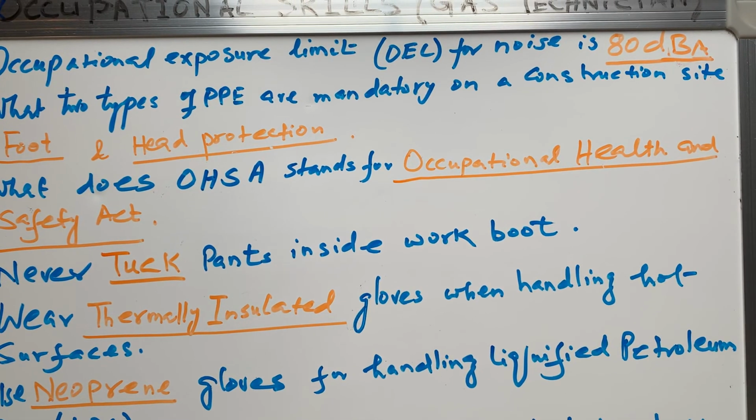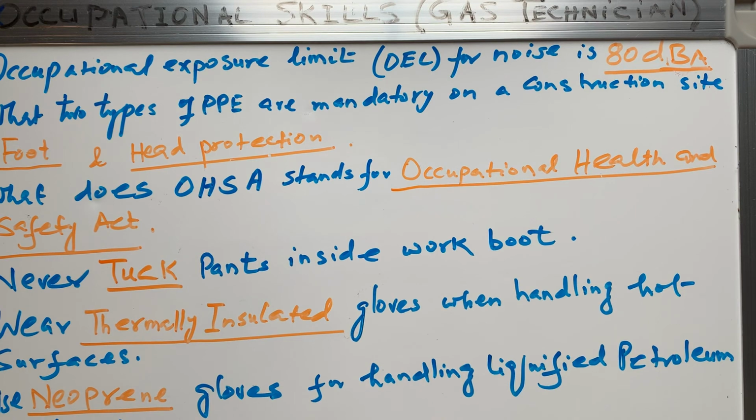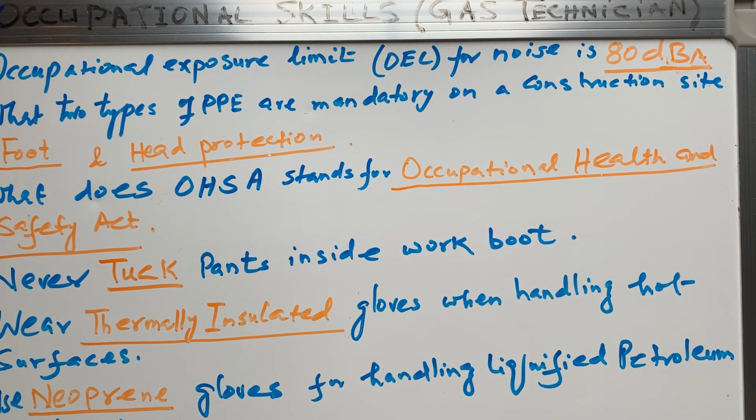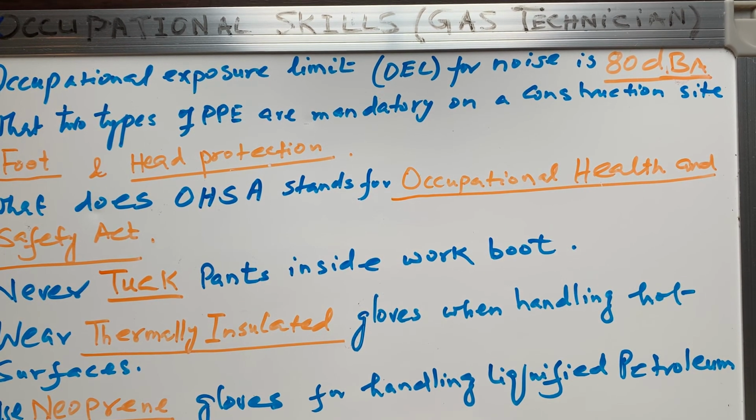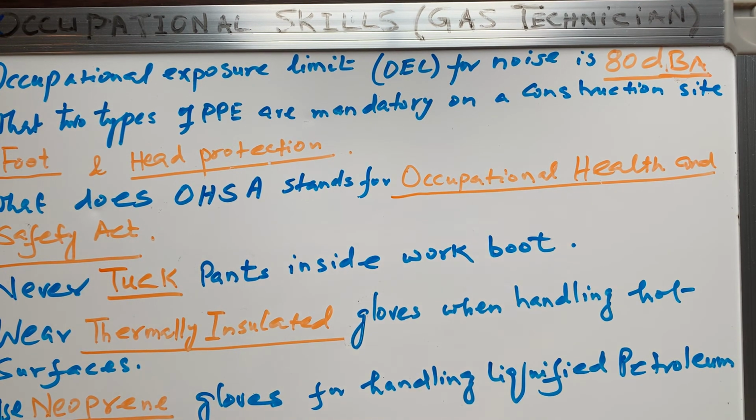Now we will review it quickly. In personal protective equipment, what have we done so far? We have done hearing protection, foot protection, hand protection, and in the last session we did head protection and how to install a ladder, right? For each 4 feet, 1 foot out. So if my wall is 8 feet, I have to make the ladder out from the wall like 2 feet.